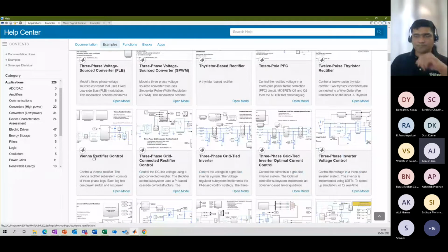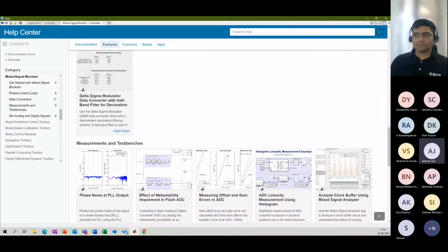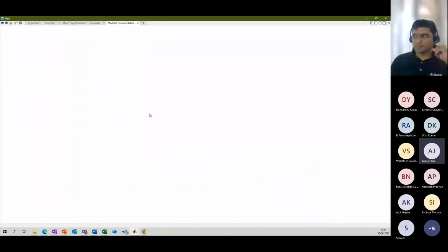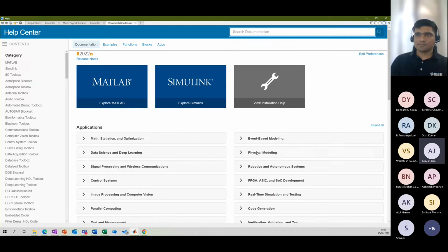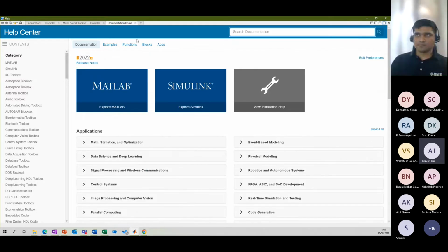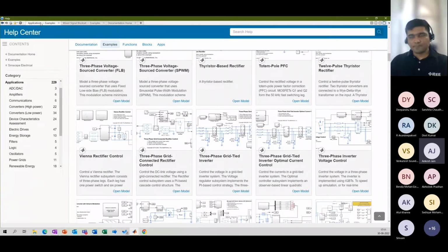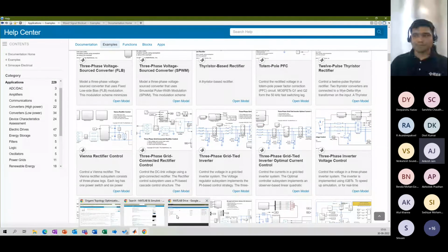No, I said that when you are developing the architecture, you are actually more at a mathematical level. So you can take help of design tools which are more at a mathematical level, like MATLAB, or there can be other open source software also. Any tool at a mathematical level can be utilized to do the initial modeling. But later on, you have to move to SPICE, because SPICE models model the actual behavior. But those models are much more complicated, so you don't want to use them at your initial modeling level when you are just developing some architecture.